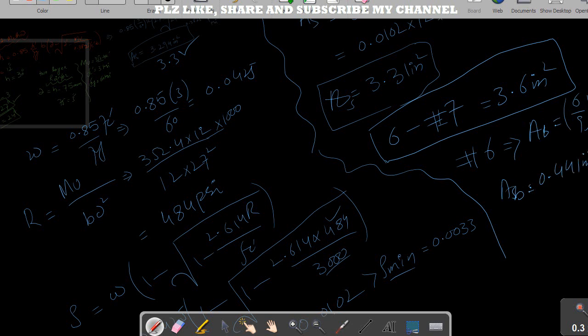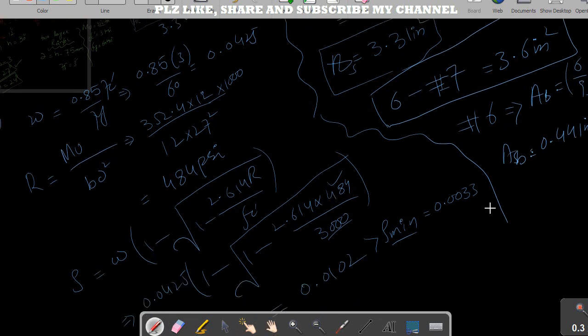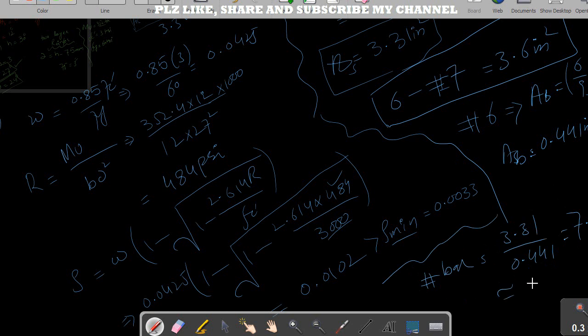Now if you are interested to find how many number 6 bars will be needed, so number of bars is 3.331 divided by 0.441, which is roughly 7.50. If we round this, so this is 8 number, 8 bars needed.